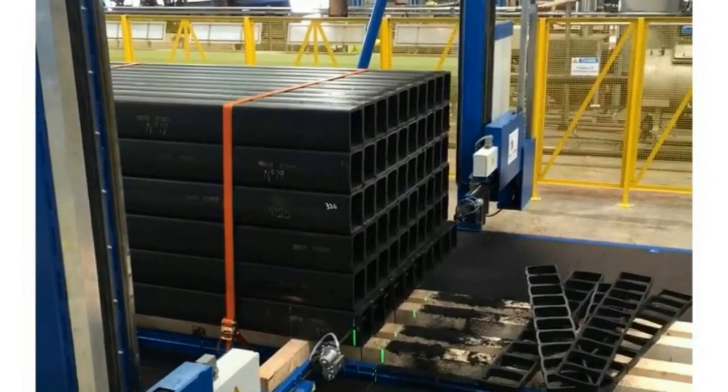Here you can see Weholite box profiles that can also be used to make flat panels instead of pipe. Instead of the box profiles being wound around the mandrel, we extrude the profiles onto a flat surface. The profiles are then extrusion welded on the ID and the OD to make flat panels. What you see in this photo is 6 individual panels that are stacked on top of each other for precision cutting to uniform lengths. These panels are used in many of our fabricated engineered systems, such as end panels for storage systems, baffle walls, manholes and pump station tops and bottoms, and modular systems for a variety of applications.